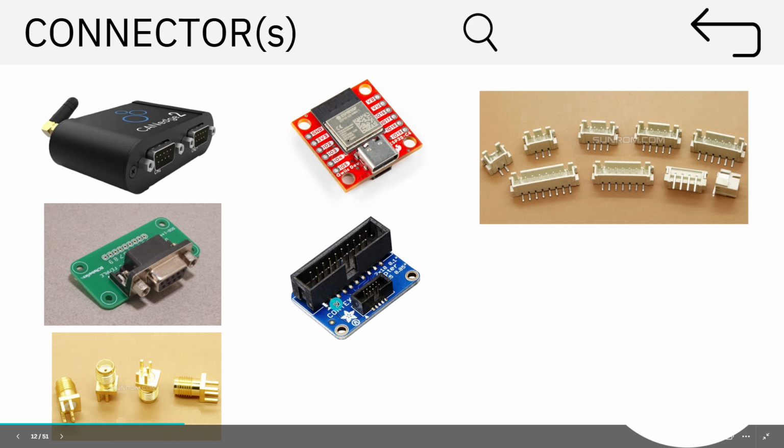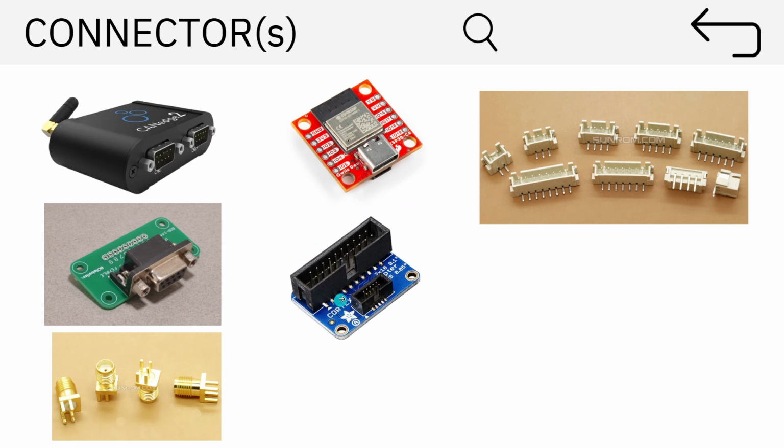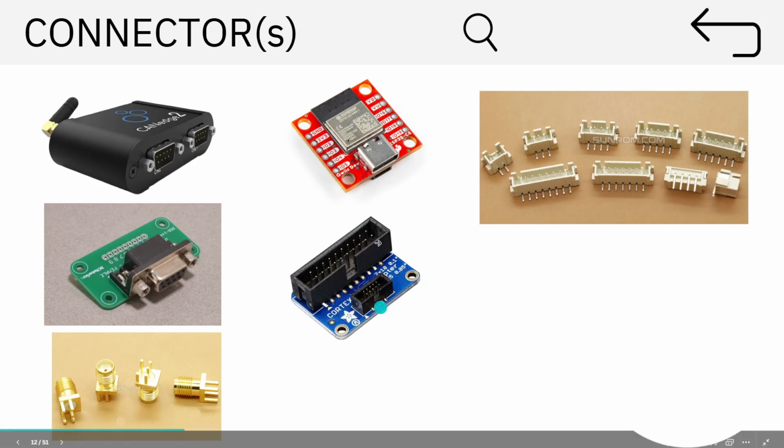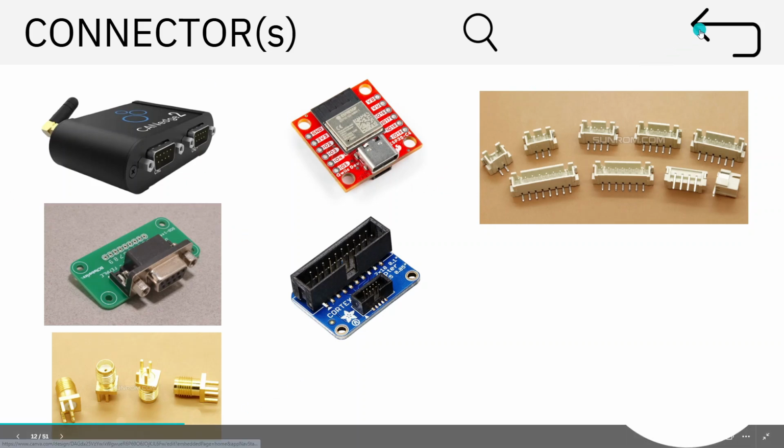Then you have a JTAG connector. JTAG will be coming in detail. These are basically the programming pins, how you can go and program. Let's say the Espressif ESP also can be programmed through JTAG, or for the ST microcontroller, you can just put a 10-pin JTAG and program it. Then you can have additional interfaces. There might be a battery connector, or some interfaces where you want to expose the UART. So this is how you have to do the whole connector requirement.